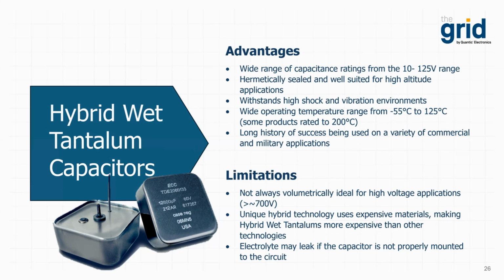They're exceptional at their ability to withstand high shock and vibration environments, and they do have a wide operating temperature range from -55 to 125 C, and some even go as high as 200 degrees C. These capacitors have a long history of success being used on a variety of commercial and military applications.